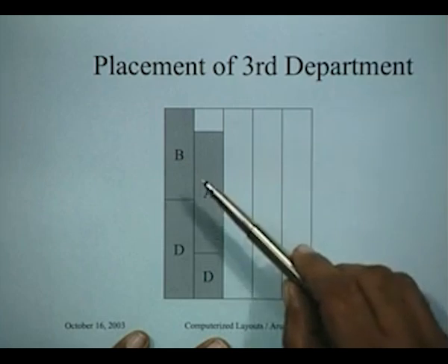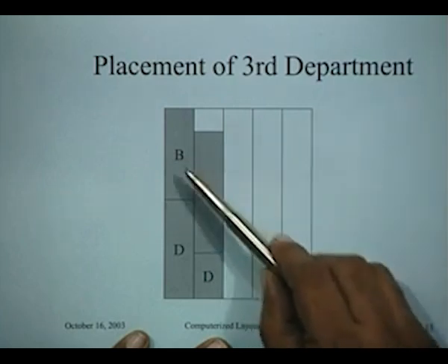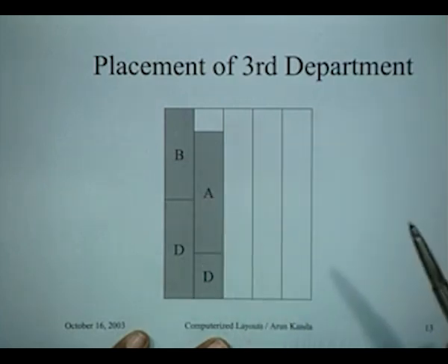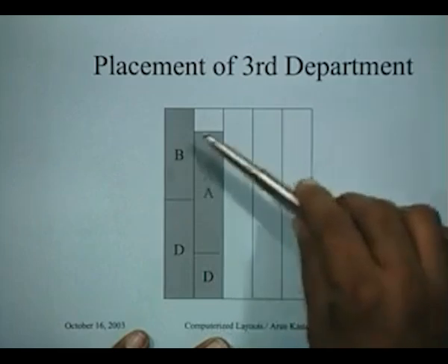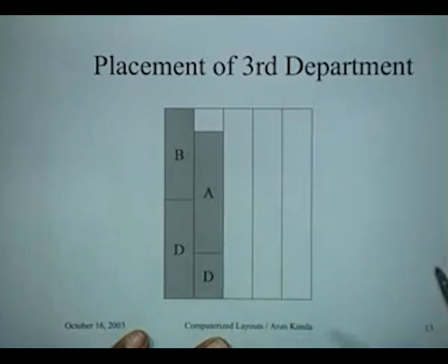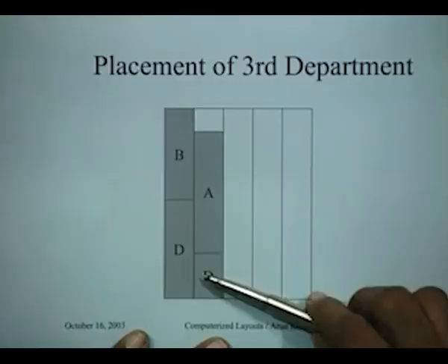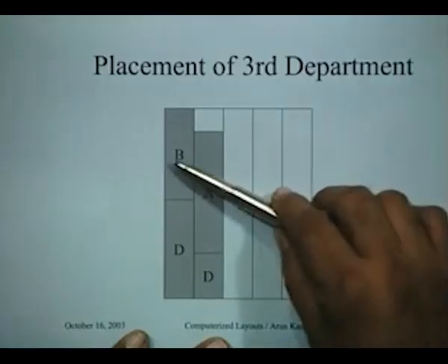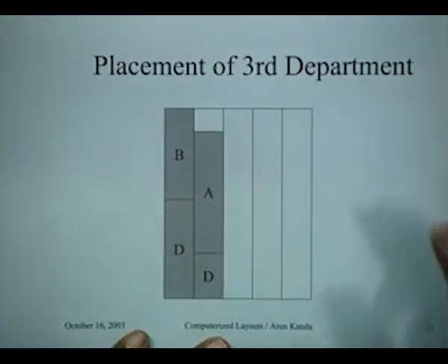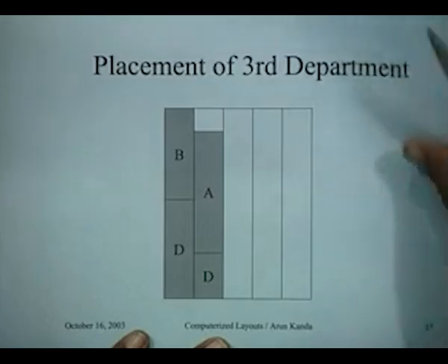It can happen that in the process of placement, A and B might not get along well, but that's not taken care of in LDEP. So that's a limitation or a drawback of LDEP. You are very right that if you keep on following this vertical scanning pattern, it may so happen that you have placed department A next to D, but the neighbors on the sides might not get along well or might have a low rating with this.